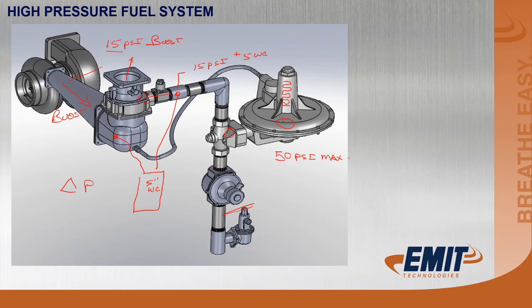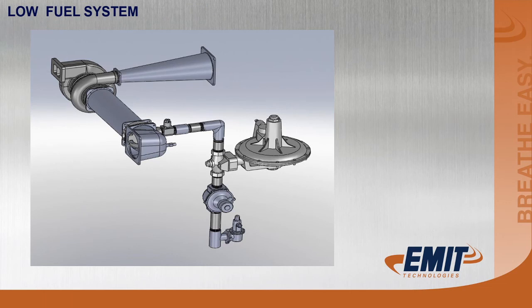So this is a high pressure fuel system. Your fuel supply is always going to have to be higher than the boost pressure. So at minimum, it's probably going to be about 25 pounds to 50 pounds coming into this to account for any losses.